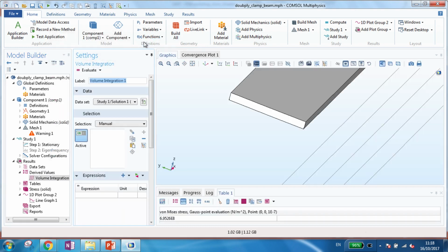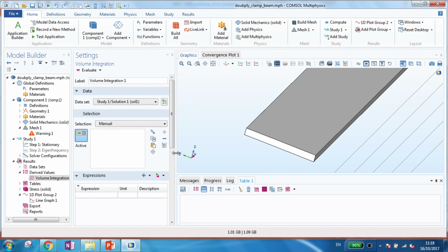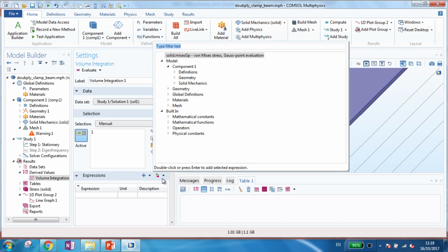if you go to solid mechanics, again, you can choose the value with this green-red arrow, and then solid mechanics. From the displacement vectors that it calculates, it can also calculate, as I told you before, acceleration and displacement. We saw the stress, but also energy and power. So under energy and power, you can see elastic energy, stored energy density, and so on.